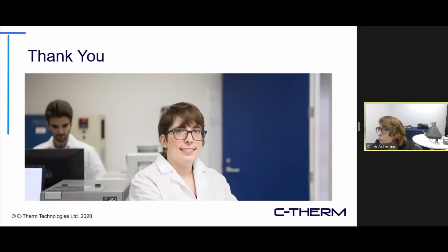With regard to the best method for filled TIMs, that's going to depend on the nature of the thermal interface material in question. If it's the kind that cures in place, like basically a thermally conductive glue, you're probably going to want something with a robust sensor like a transient line source, so that the material can cure around the sensor without causing damage to the sensor material.